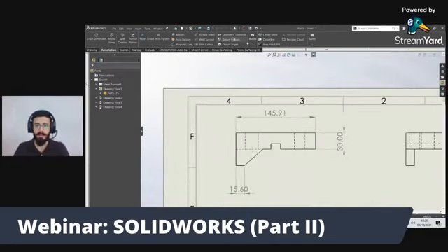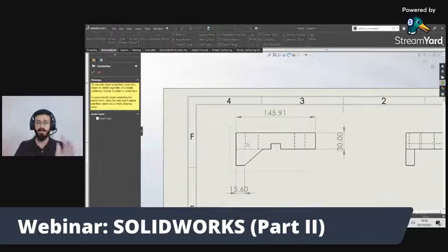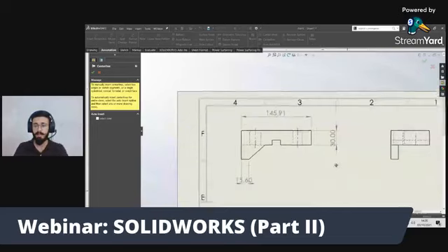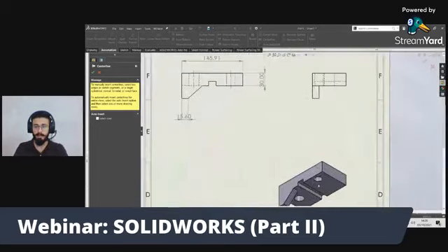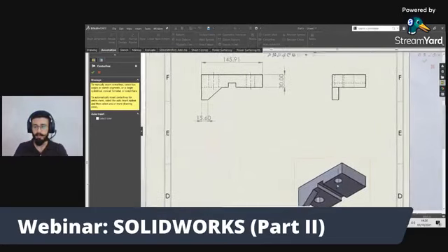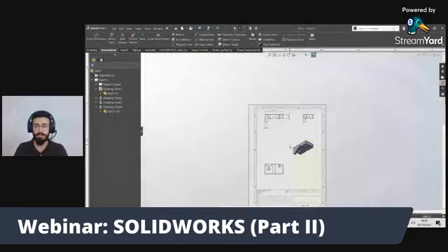Center mark, like there is a circle, but maybe people think there is just a cut. I will add a center mark, so the fabricator should know that there is a hole. I will just add the center line here. And from here, it's already done, and I can add here also. See, there is a center mark here. That's how it is done.